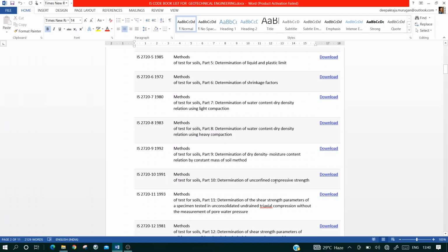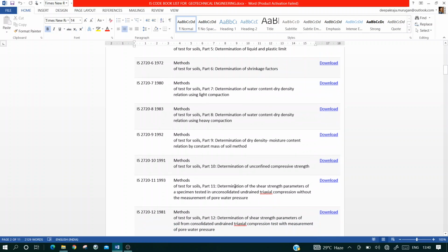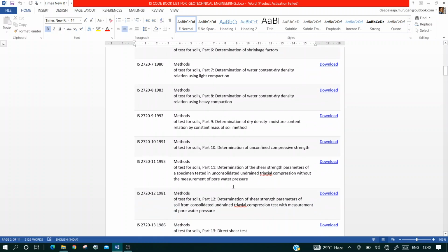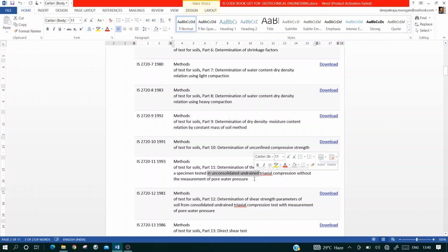Okay, the UCC test, you will be knowing, can be conducted with the help of IS 2720 Part 10. And Part 11 deals with the triaxial test for unconsolidated undrained parameters.